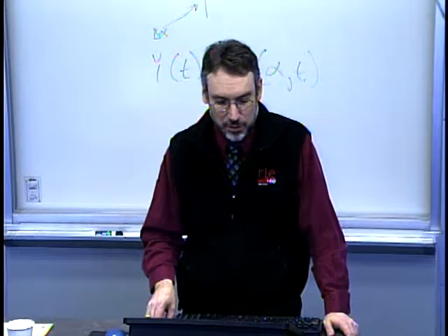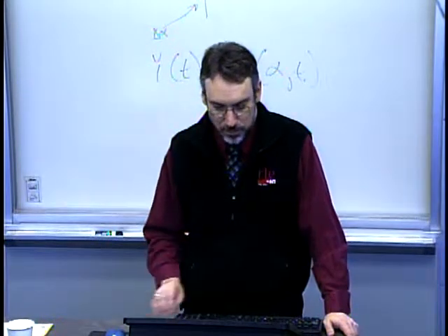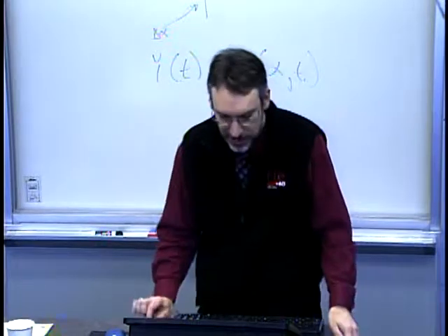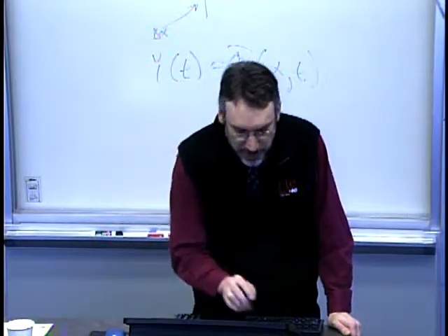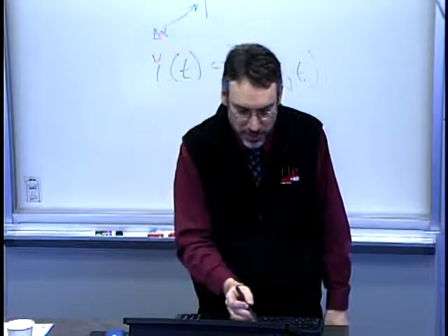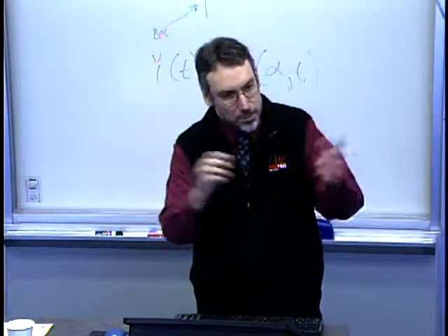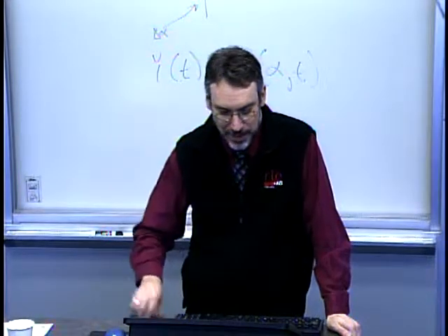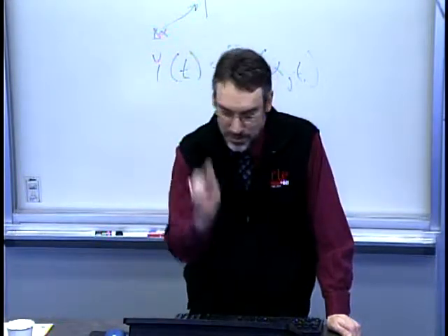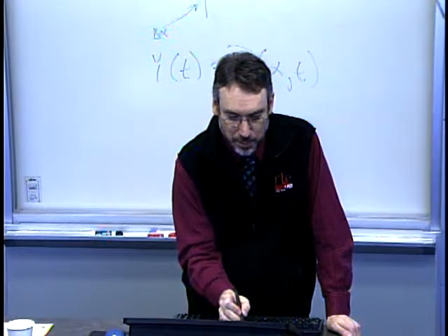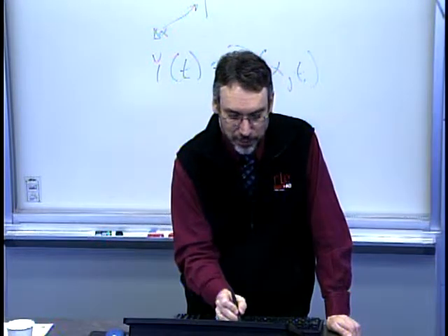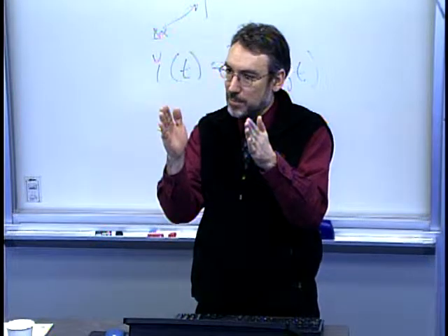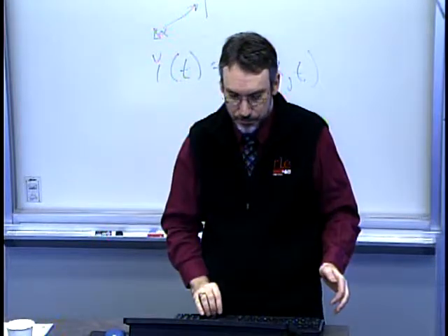So, for example, a way of, let me jump forward here. This is some thermoforming data. Again, this is some dimension, and then over this collection of parts, we have a sort of this bar chart, this frequency histogram. And what that's really saying is for each of the bins in that histogram, I'm simply plotting the frequency or relative frequency that some output was between the bounds of that bin, right?